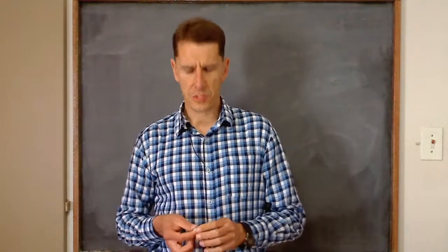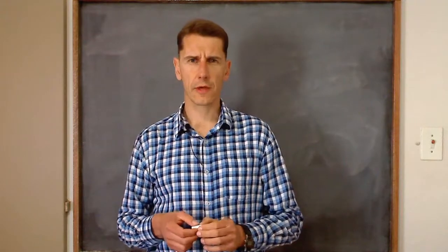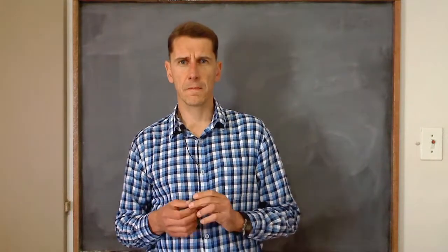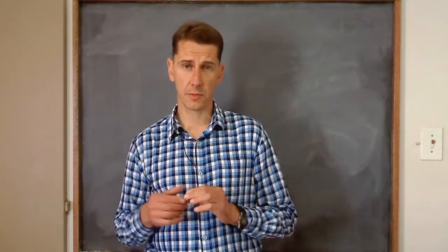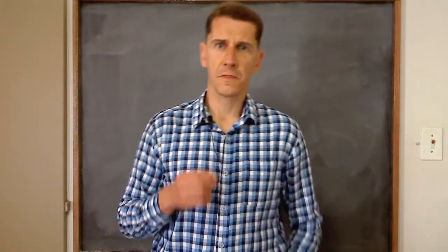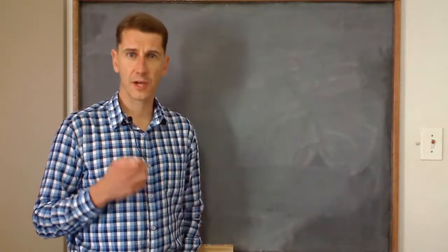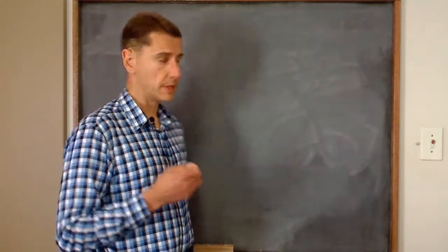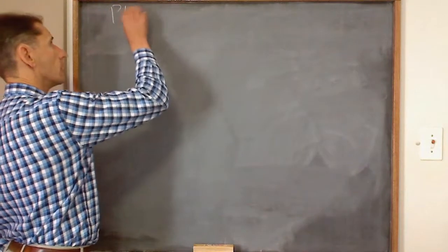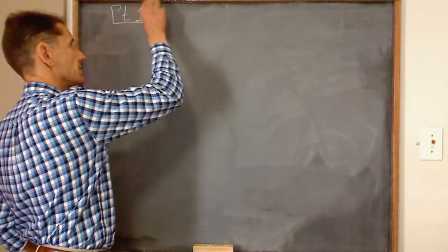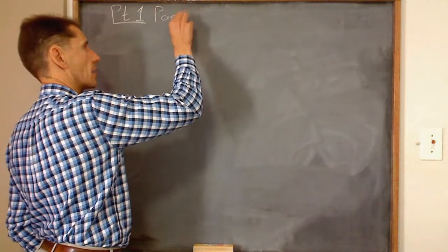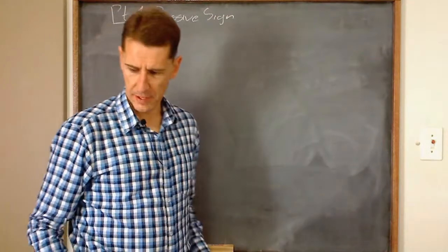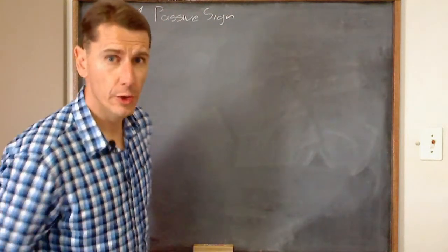So while we're going to do chapter 8.2 and we're going to learn how to calculate those initial and final conditions for RLC circuits, there are two key points that the textbook also mentions that we need to take into account. The first key point is the assigned polarity, or the passive sign convention that we need to apply. So point 1 is just passive sign. Now I know we've already spoken about this as we went through, but here it's going to become absolutely critical.